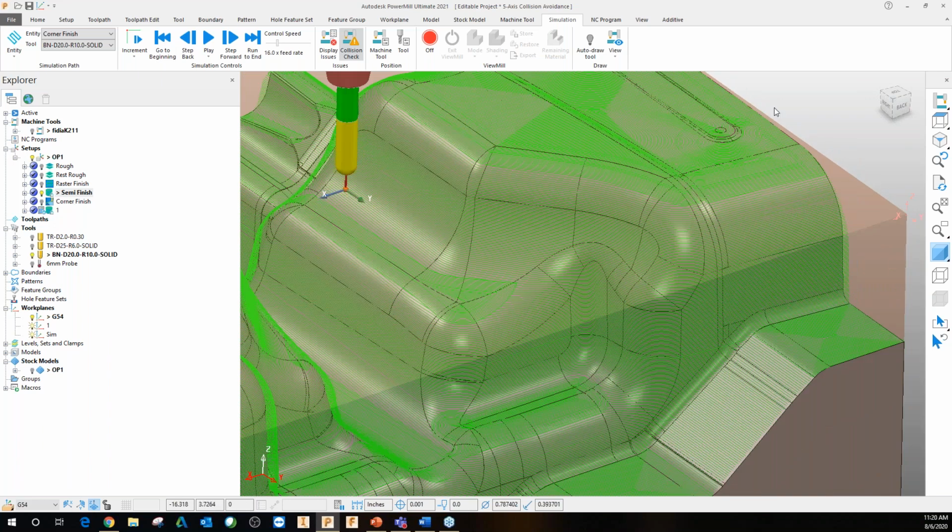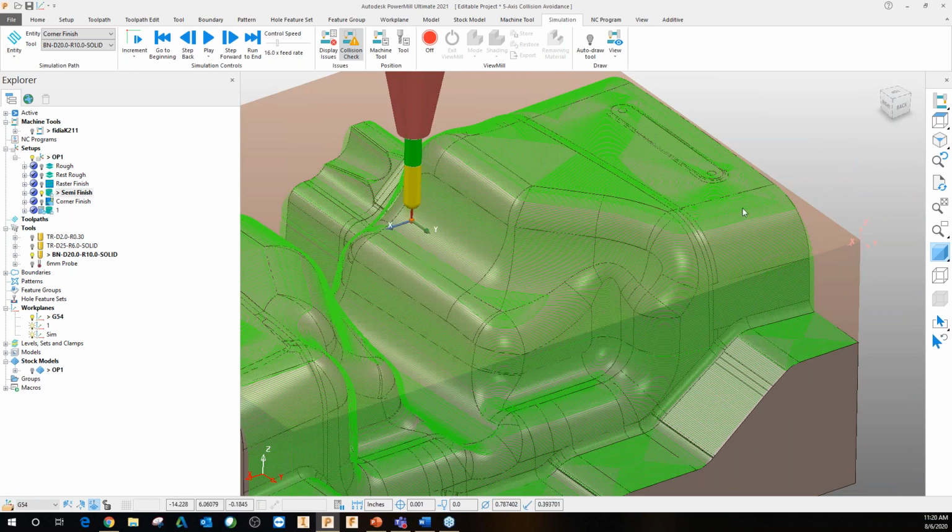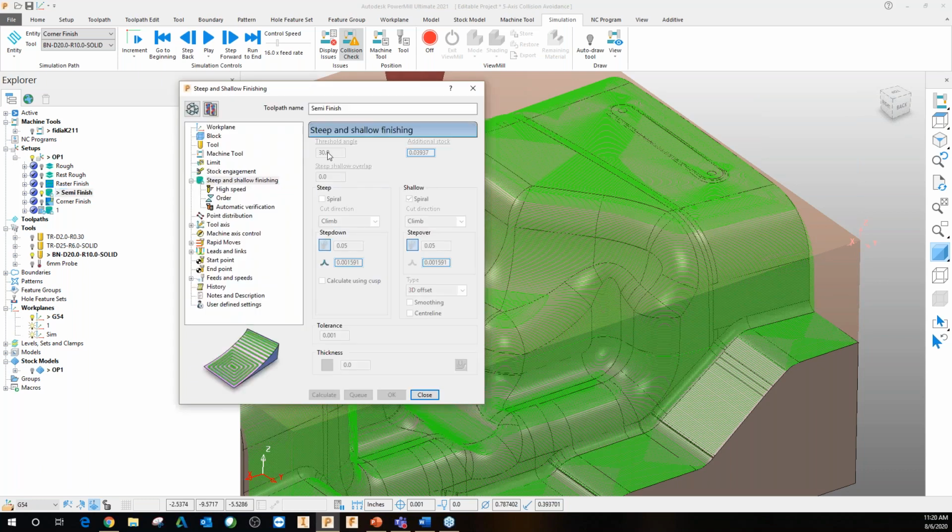So this is a way that PowerMill is going to automate the actual toolpath itself, so that you don't have to go through and look at this part and set boundaries and figure out, where should I be using the contour, where should I use the scallop. It automatically determines those for you and builds a very smooth transition. So the way this is controlled, just a quick high-level overview, is what's called the threshold angle.